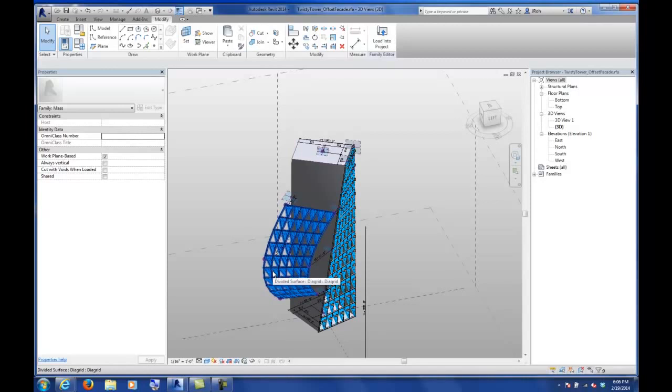And there's another thing we can do, which is called adaptive components. Adaptive components is where you can actually make your own pattern and then place it either on a grid that has nodes associated with it, or you could use it as basically a kit of parts that you could start to draw. I'm going to make this pretty simple actually by going into our view.